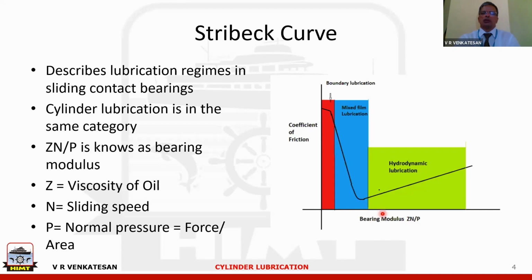Then why should the coefficient again start increasing after this? This is because of viscous friction, not because of metal to metal contact. It is only because of viscous friction. So as the oil film becomes thicker, within the oil film, friction will be more.